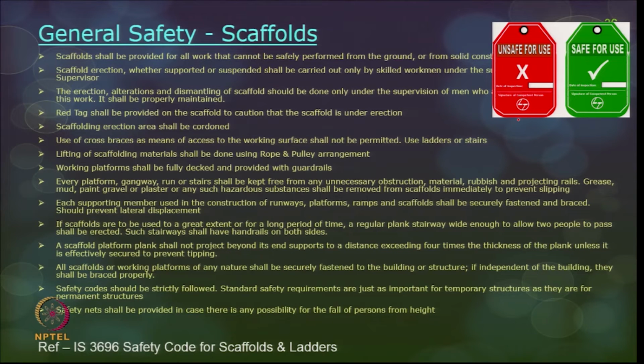And every supporting member used in the construction of runways, platforms and ramps should be securely fastened and braced, because that should prevent lateral displacement. If the scaffolds are to be used to a great extent for a long period of time, then a proper staircase or stairway wide enough to allow 2 people to access the scaffold should be laid down, and these stairways should also have handrails and adequate safety precautions from falls.